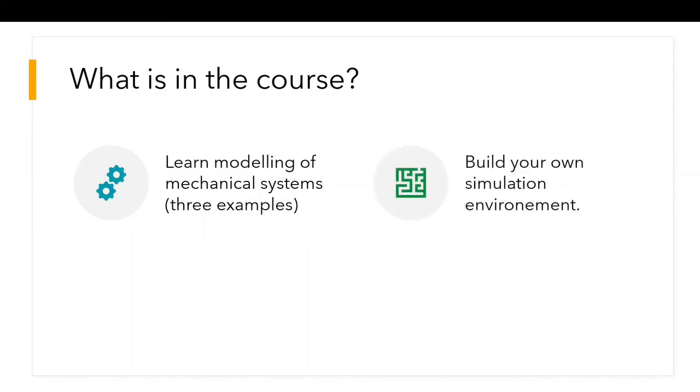You will learn how to create a simulation setup to simulate your system in Python. You apply a step input to the system and simulate it for a few seconds. You will learn how to apply control to the open loop system. In our examples, we have used PID control, but it's not limited only to PID. You can apply any type of control strategy to this simulation.